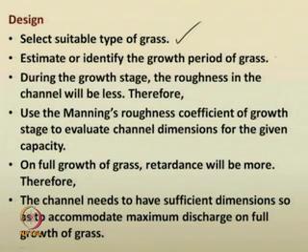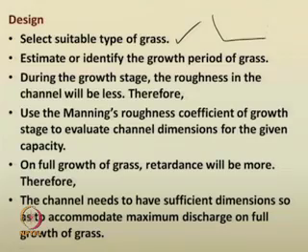Unlike other lined channels, for example wood or concrete, where once you do the lining there will not be any change in the lining, that is not the case for grass. Once you lay the seeds of the grass, it will take some time to grow, and during the growth stage it will attain different heights. So, during the growth stage its roughness will be different at each time interval, on the bed and on the sides.